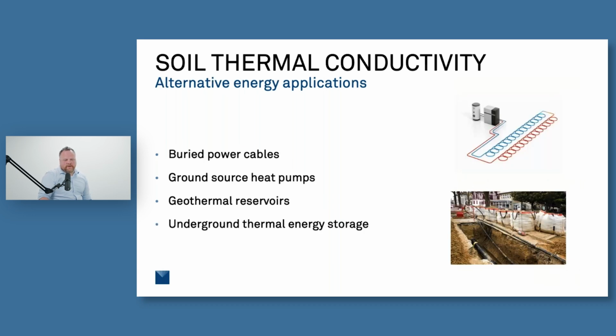And then finally, our last one that we're going to talk about right here is alternative energy applications. So a lot of alternative energies such as solar and windmills rely on buried power cables to get the power from the source to us. And those buried power cables carry a lot of current and a lot of voltage, and they heat up quite a bit. So you need to make sure that the materials surrounding those cables are able to handle that heat load and transfer it away from the cables.